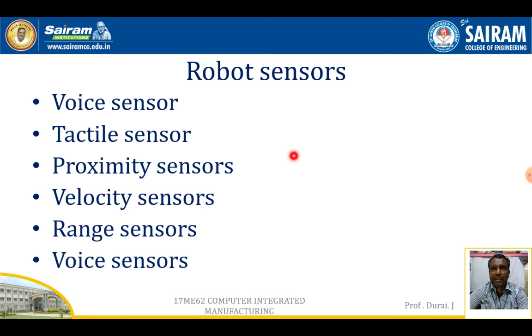Sufficient light source is beamed on the object to be sensed. The video camera is mounted either on the robot or in a fixed position above the robot, so as to cover the full work volume. The signal is sent from the camera through the frame grabber and processed by the computer, and based on that the robot system senses the presence and location details of the part to be handled.